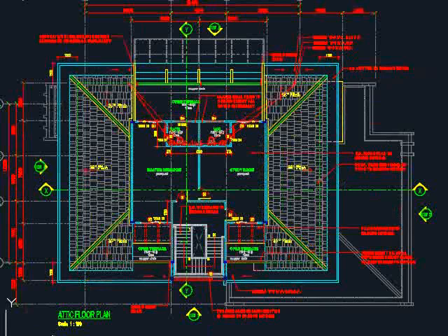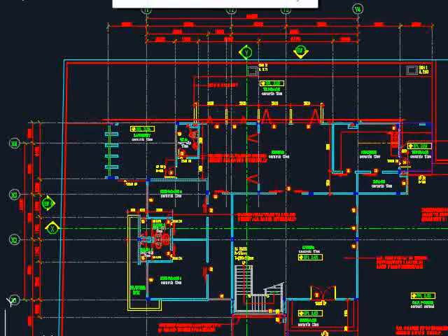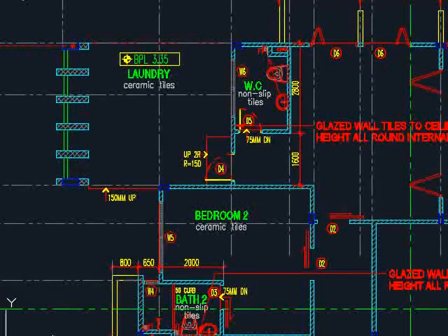In this architectural drawing, you have an attic floor plan, which is above the roof plan. From the floor plan, you will see the grid lines, and the dimensions of the grid lines are given together with the numbers of the grid lines. This line will serve as the alignment or construction line for the buildings to indicate the positions of the walls, the size of the space, and so on.